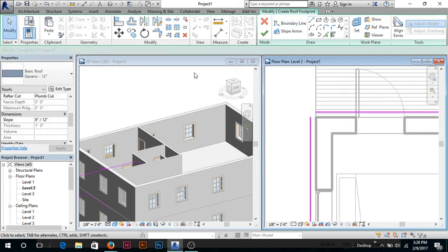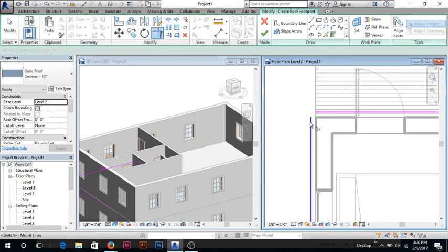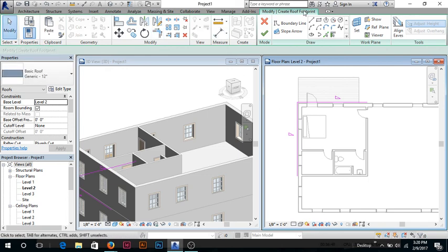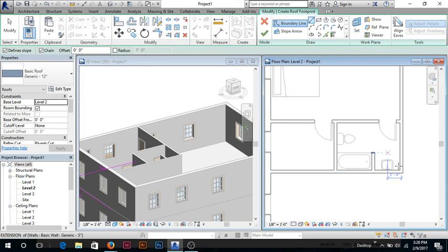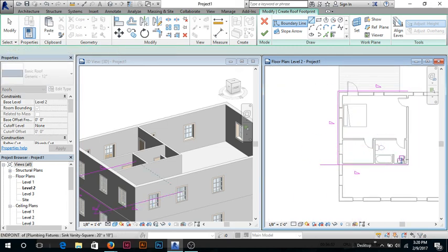These lines don't connect. I can simply just click on one, click on the trim tool. So click, and there you go. And then click on that line again. My offset's 0, perfect. Just click, extend it out, escape, click, extend it out, escape. Now you got to trim this stuff up, so just simply go to the trim tool again, click, click, click, click, perfect.